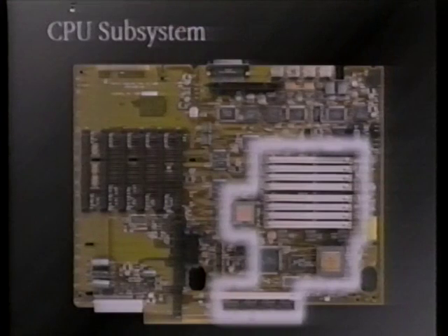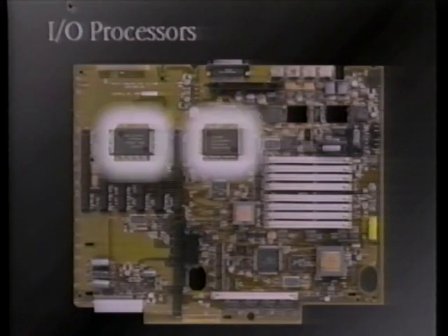So what we've done is added a sophisticated, totally integrated, brand new I/O subsystem. The first components of this are brand new custom chips, of which there are 7 new custom chips on this, all designed at Apple, called I/O processors. These are standard cell implementations of the 6502 CPU. The best way to think about these is we have 2 surface-mounted Apple IIe's on every IIfx logic board just to provide I/O performance and consistency.